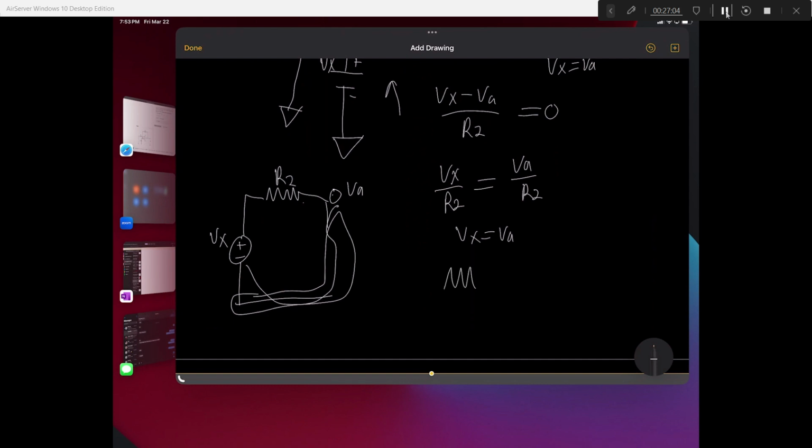Say you have two resistors. How is this any different? Well, if you had a battery here, and they're connected, say there's a voltage drop across this, current times resistance, and you get like 4 volts, right? And this is 20. Well, this point here is going to be 20 minus 4, because there's a 4-volt voltage drop, and you're going to get 16 at that point.